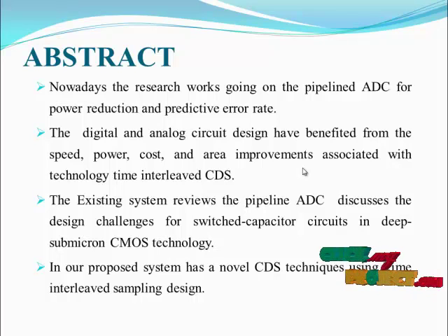This reduces the accumulation of prediction error of each multiplying operational amplifier without the need of additional capacitors and switches at the output. With a 10 MHz sinusoidal input, a prototype fabricated in a 0.13 micrometer CMOS process has a 56 dB signal to noise plus distortion ratio, that is SNDR, and a 64.57 dB spurious free dynamic range.